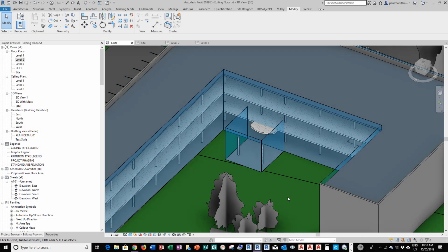Now, what happens if we have another floor opening that you want to match up on the upper level, like in level 3? We have a stair opening here. We probably need another stair opening on the level 3 floor slab so that you can get from level 2 to level 3. And what happens if you have more than 2 or 3 levels? If you have 15 levels, what are you going to do? It's probably not the best method to go to each floor slab and sketch the same stair opening profile in each floor slab, because when it changes, you have to go through all the floor slabs and update the sketch profile.